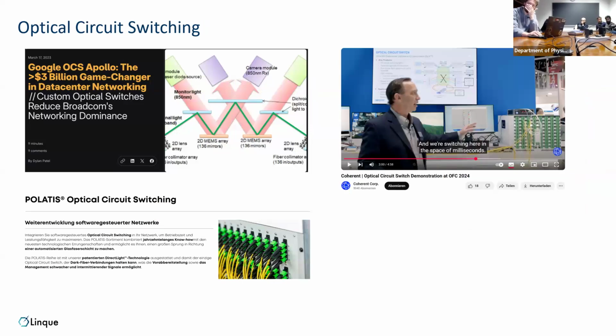Yes, and as I said, this is a little bit more interesting because it's actually used in industry. So-called optical circuit switching is used in data centers as a way to replace, at least partially replace, Ethernet switches. Because an Ethernet switch for optical fibers in a data center is basically a high-performance computer, right? You have an ASIC chip inside that consumes like a kilowatt for like 100 channels of light,